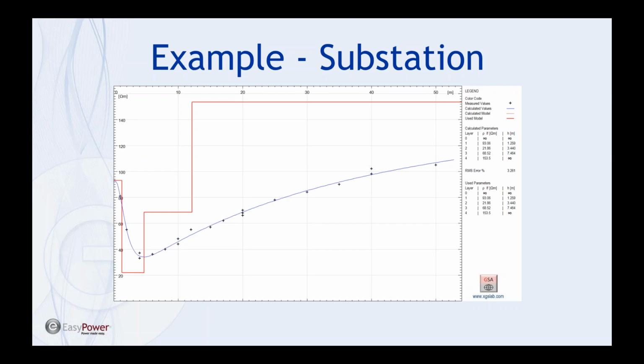The next thing that you would do in a grounding analysis program is determine the soil model that you apply to the preliminary grid that you've imported. What's your grid sitting in? What we're showing here is a multi-layer soil model, based on soil resistivity measurements. The black crosses represent the measured values of soil resistance for each spacing, and the blue is a curve fit on top of those. The soil model, finally, in red, is one that has been calculated based on the measured values. The program iterates until it finds the model with the least error.